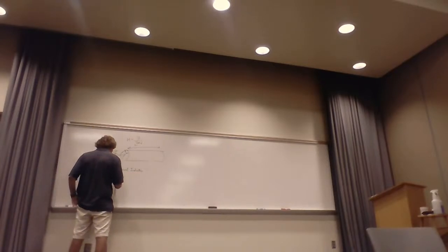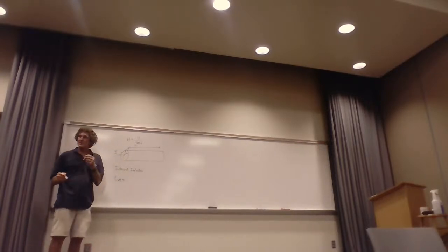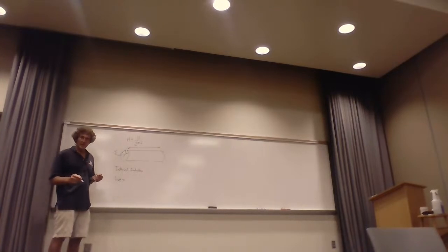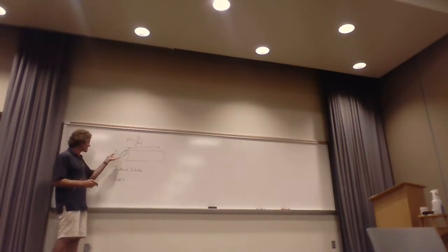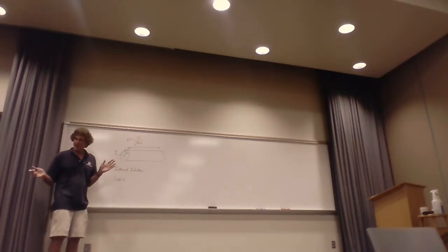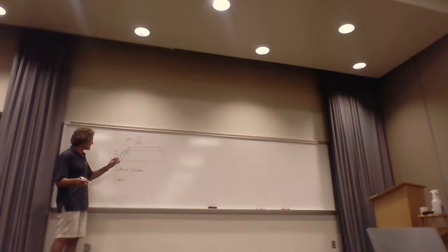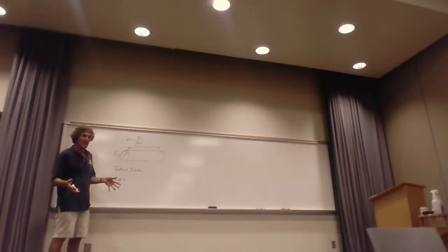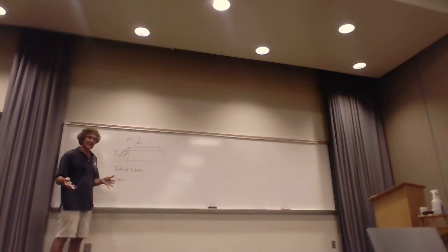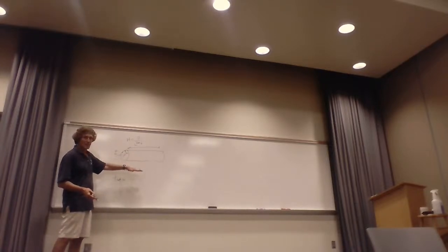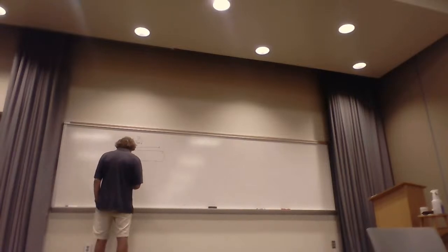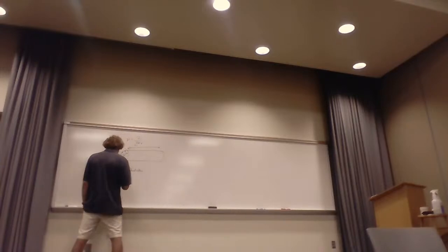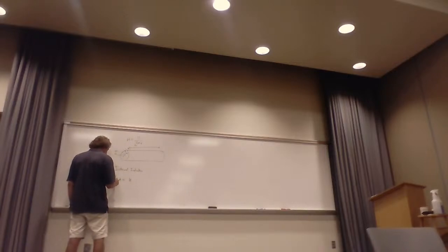it's usually called L sub i in his book, for internal. For DC, I don't know if you remember this, but the internal inductance was not a function of the radial distance a. That was per meter. It is proportional to length, but it is not a function of a, and that should be shocking, but it isn't. It falls out because the magnetic energy gets spread out in the same amount. So for this, it's going to be proportional to mu, then proportional to the length, and I'm going to do this per length. So internal inductance, it'll be per meter.